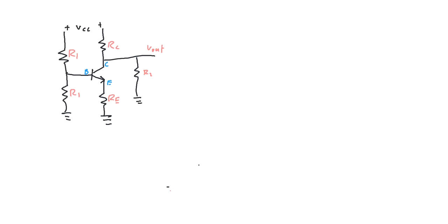This is how you might actually build it. You might actually build this circuit just like this, with this bias network of R1 and R2 to produce some kind of voltage at the base, VB. You could easily build it that way. But if you look on a data sheet or some instructions, they may not tell you that that's what it is. They might give you something more like this.